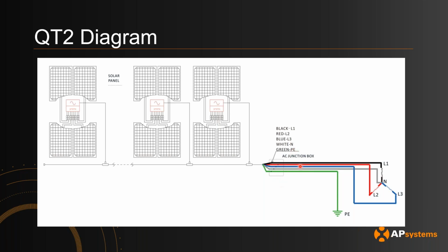It's actually okay if you're using your home run to just use 3 wires and not connect neutral and ground, unless it's necessary from a code perspective that you need to run neutral. Neutral is not necessary for the system to provide power. Ground is also not necessary because usually you're grounding from the rail, so you don't need to use the bus cable for grounding.